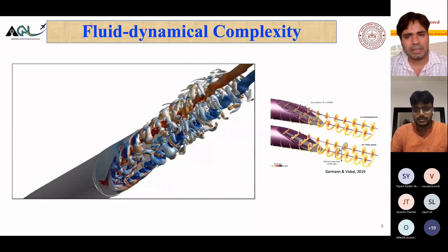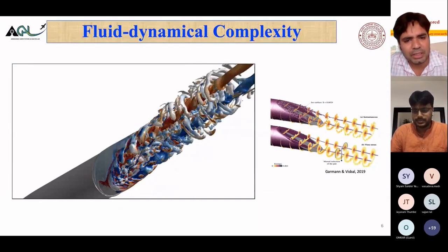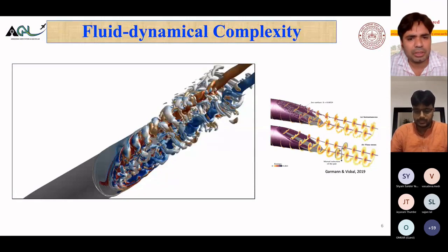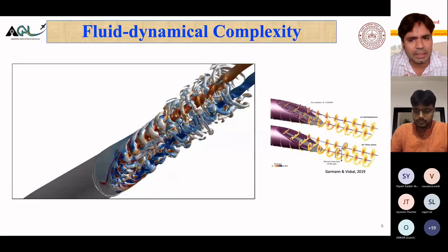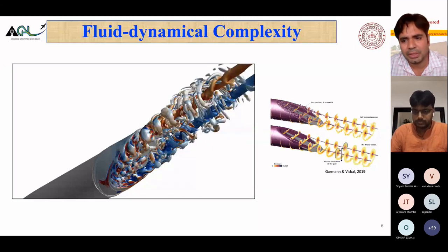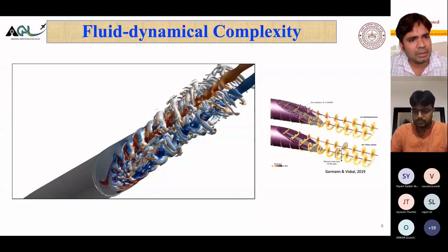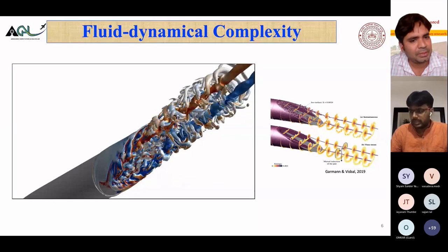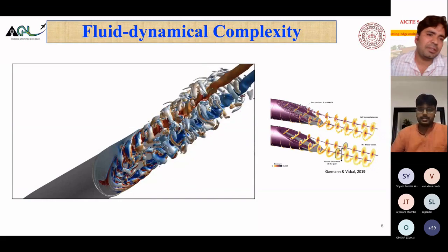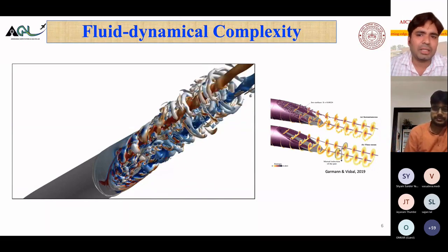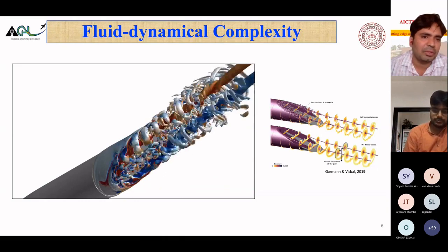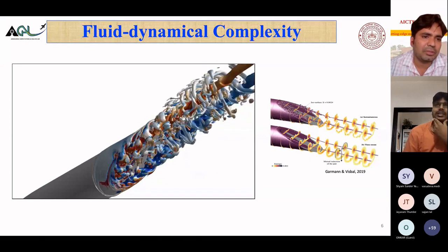Okay, one thing I would like to ask: let's say someone is using proper orthogonal decomposition, POD modes, before going ahead with their actual analysis to judge how complex my flow physics is. So they need some kind of data, right? Probably experimental data, if they have it. So what is the minimum number of frames someone needs to do some kind of pre-analysis regarding the complexity of a flow?